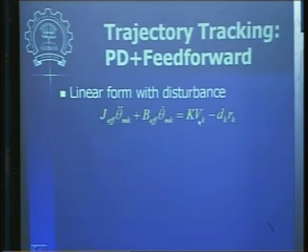So what we can do is estimate what these terms are along the trajectory, and then compute that estimation and put it in our control. Because we know that for a given trajectory, whatever is theta md, we have to overcome these forces.